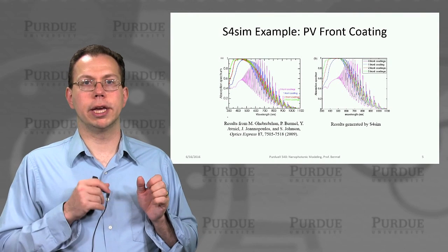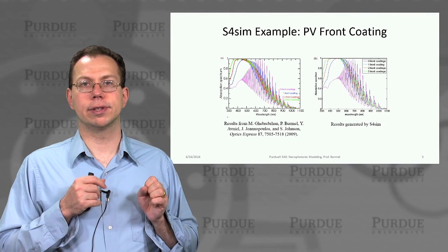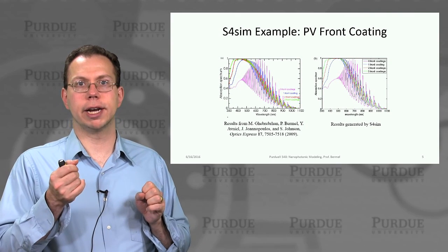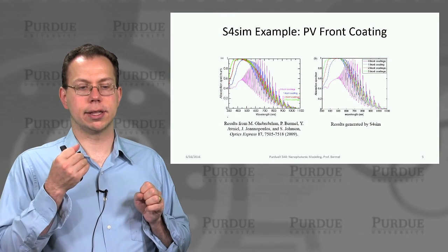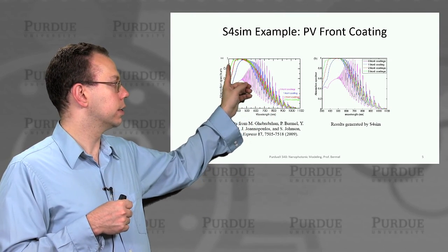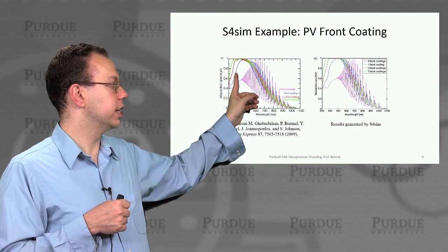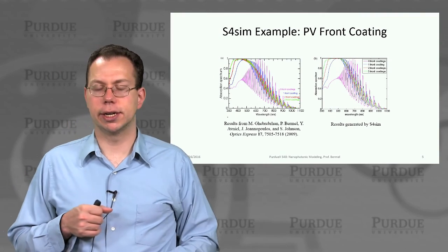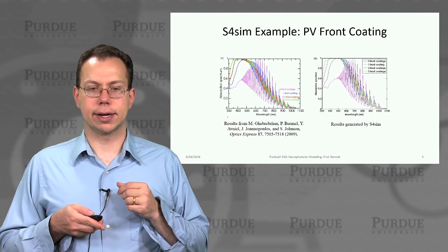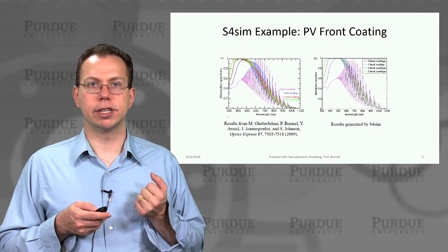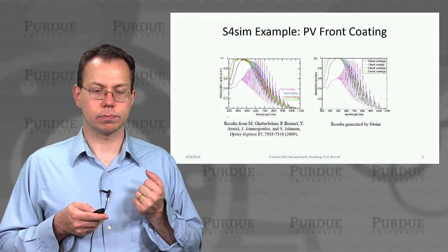You may or may not be aware that a lot of solar cells actually look blue. This is a physical manifestation of the fact that they tend to reflect blue with just a single anti-reflection coating, which has this kind of absorption curve here. But as we add more layers, we suppress that blue reflection, and the cell would actually look black at that point, which is better in terms of getting higher efficiencies and short circuit currents.